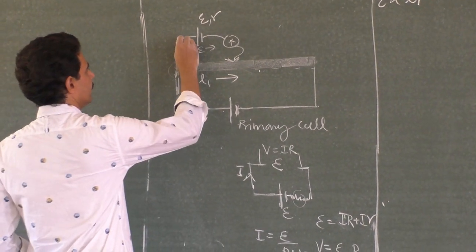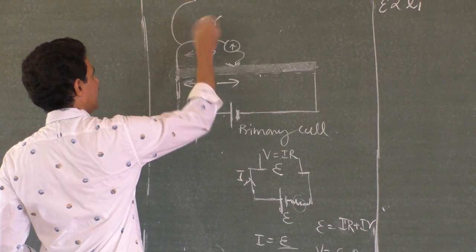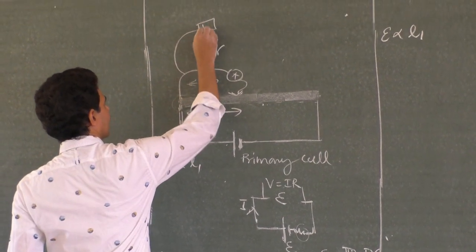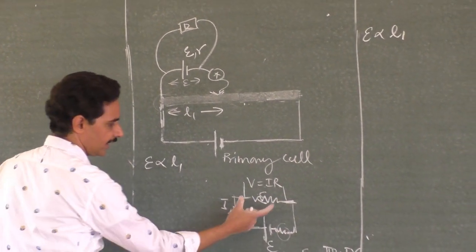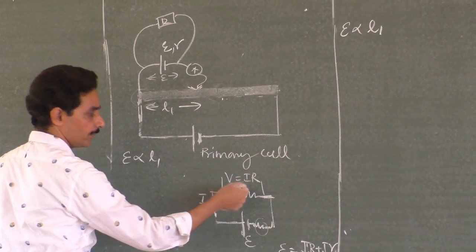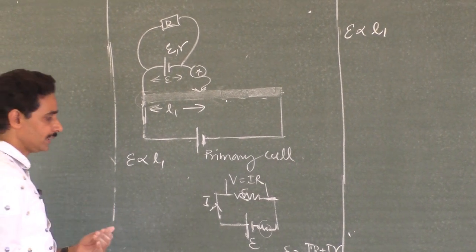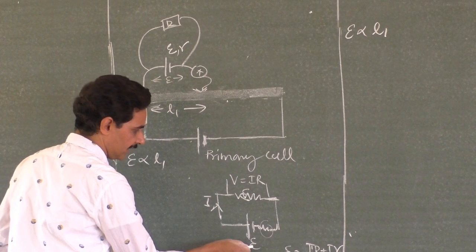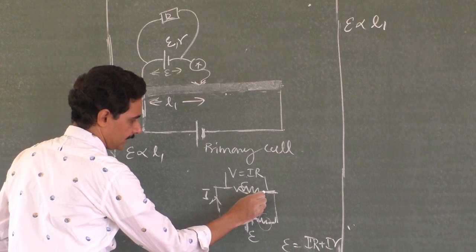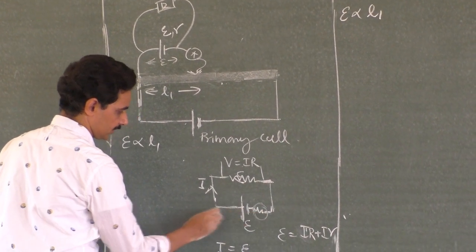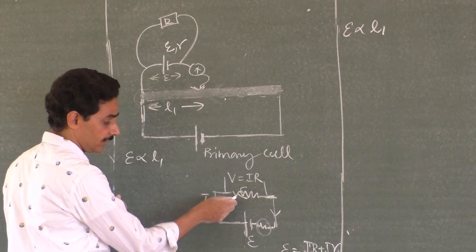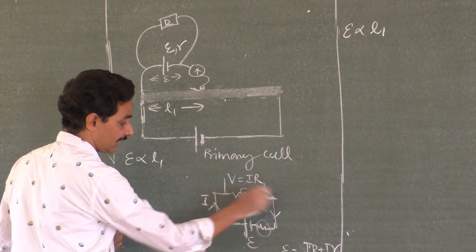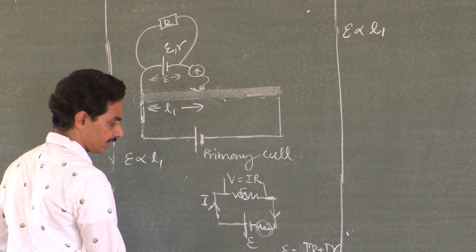Connect this battery across a resistor R. When you connect this R, suddenly the voltage here drops from EMF to some other value. Why, sir? Out of this EMF, only some voltage is available here. A small voltage is dropped across the internal resistance because current starts flowing. Last time the full EMF of E was available because there was no drop here. Now current starts flowing, and a small drop appears across this.